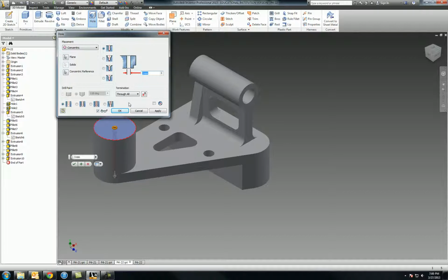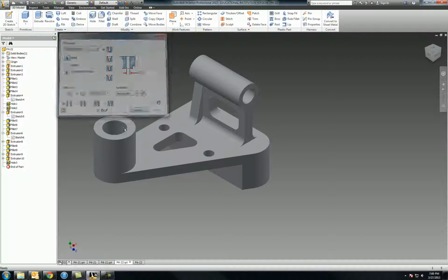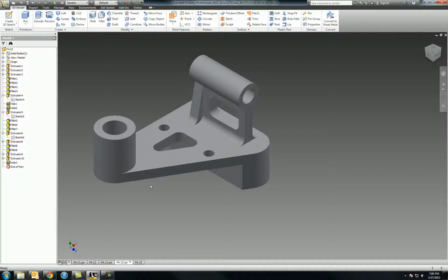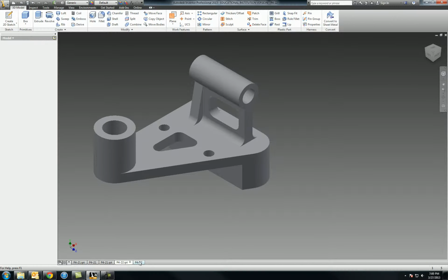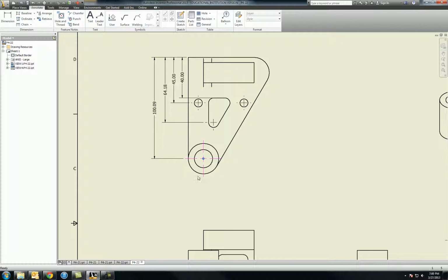During the drawing process, it's very easy to find mistakes. When you find mistakes during the drawing process, the very best thing you can do for yourself is to go through and fix those mistakes. Now when I switch back over to here, this dimension is no longer valid. You can see the pink line. That means that center line was placed to geometry that no longer exists. So I'm going to recreate my center line on this piece and redimension it. And now the new dimension, if everything else in that sketch is right, should come up at exactly 100.